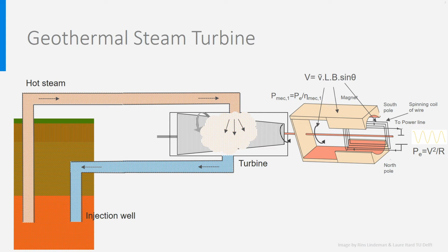However, there are many other locations in the world where the ground temperature is much lower than 200 degrees, making it impossible to make steam with a pressure high enough to drive the turbine. This problem is solved by using closed cycles using a refrigerant with a boiling temperature lower than that of water.